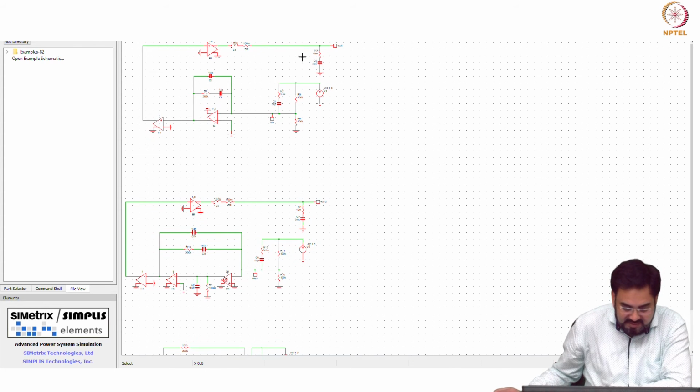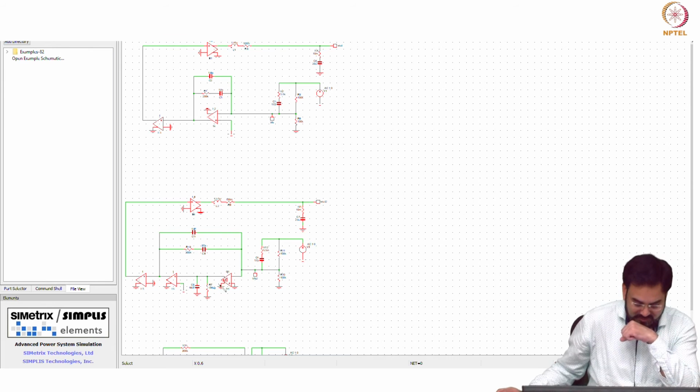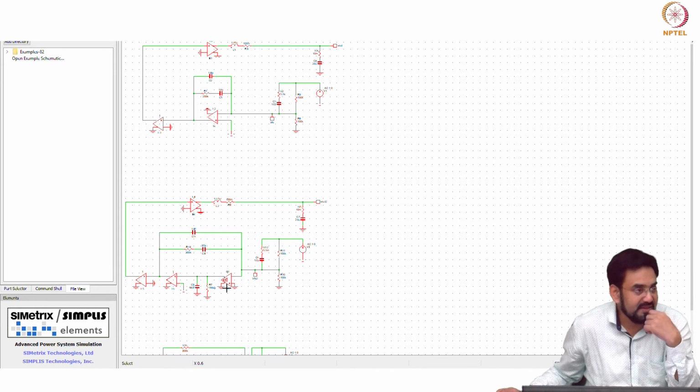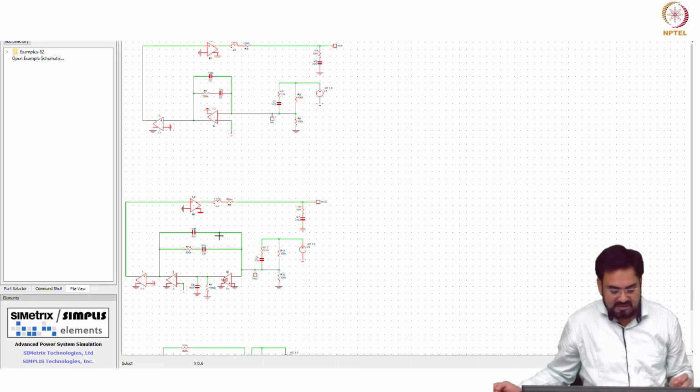So what I did, this was my original circuit, and I replaced this op amp with the first order model. So you have a voltage controlled current source, then I have RC at the output. So GMR will be your gain. I'm keeping 1 milli and 1 mega, so it's a 60 dB gain, and the same 1K here. So I try to keep the same, and then you have a buffer to make sure this 1 mega ohm is not loaded with that at high frequency.